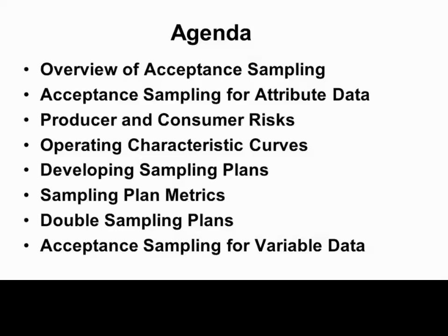The operating characteristic curve, or OC curve, is an important function which really dictates how a given sampling plan will perform in terms of what kinds of quality levels it will routinely reject or accept, and where there is uncertainty. Essentially, we're going to pick 2 points on that curve and fix them and identify the errors that we could make at those 2 levels of quality.